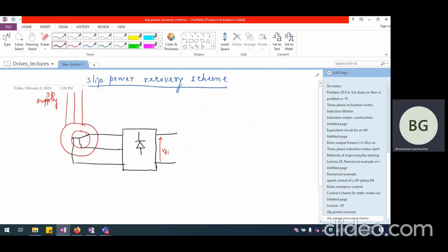Now, we are going to have another thyristor converter connected on the other side. And just to avoid the instantaneous voltage differences magnifying the current that is circulated through this particular link, we are going to have a reactance or an inductance, which is actually DC side inductance. Now let us say this value of voltage is VD2.